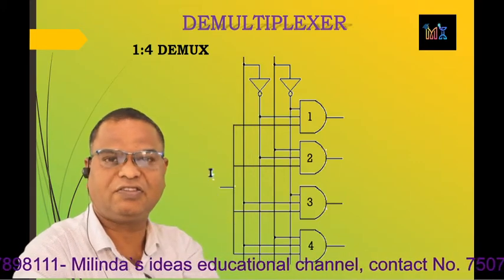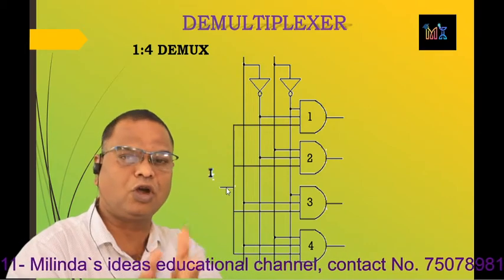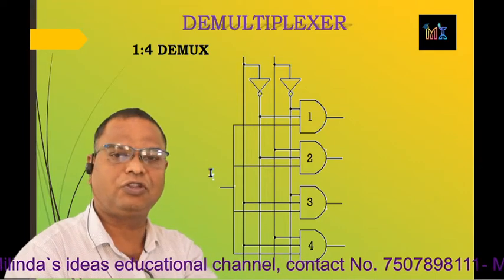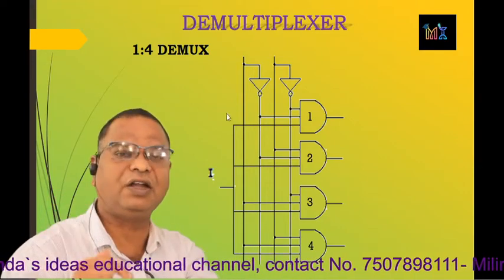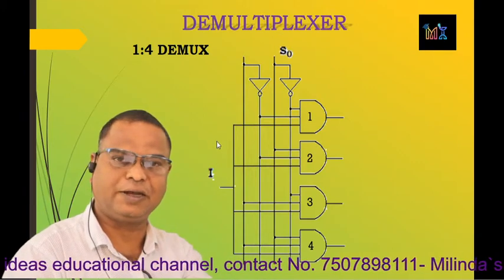And in this case, 3-input AND gates are used because there are 2 control lines, that is S1 and S0, and 1 data input. So in this case, a 3-input AND gate is required.